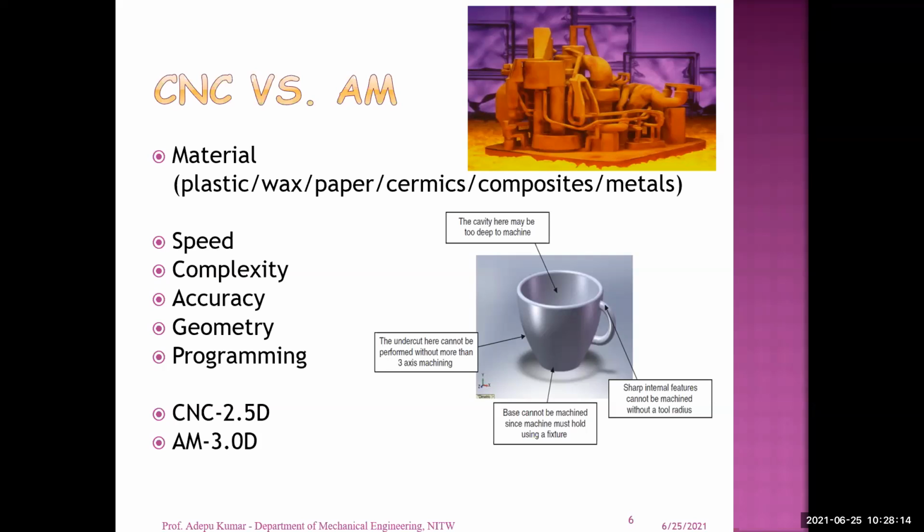The micro channels are produced in computer peripherals as well as other defense and aerospace applications to increase the heat transfer rate. Then how do you generate the micro channels? The channel may not be straight. There should be some irregularity. To increase the heat transfer rate, I can go for more complex micro channels. In such cases, a conventional machining process may be suitable, but it takes a lot of time, and the accuracy of the component generated through machining is very difficult to achieve. The additive manufacturing is very simple. Even internal micro channels or external micro channels, it doesn't matter.